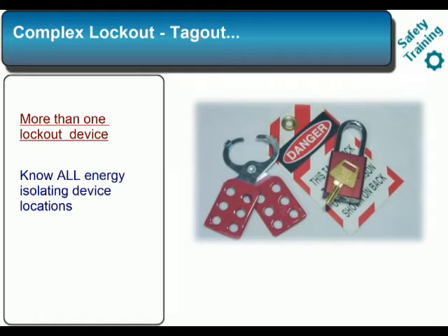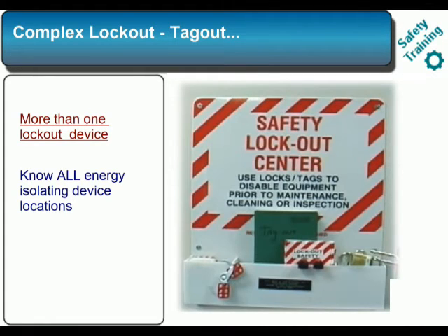Duplicate keys to your locks are not allowed. Only you should have the keys. Be sure to use only company-provided locks and tags. More locks, tags, or locking devices are available either from your supervisor or from a Lockout Tagout center. If you don't have what you need for a full lockout, tagout, tell your supervisor.